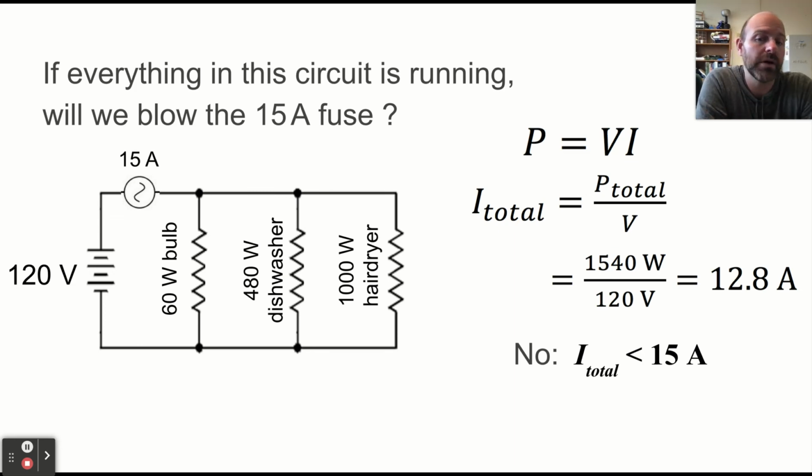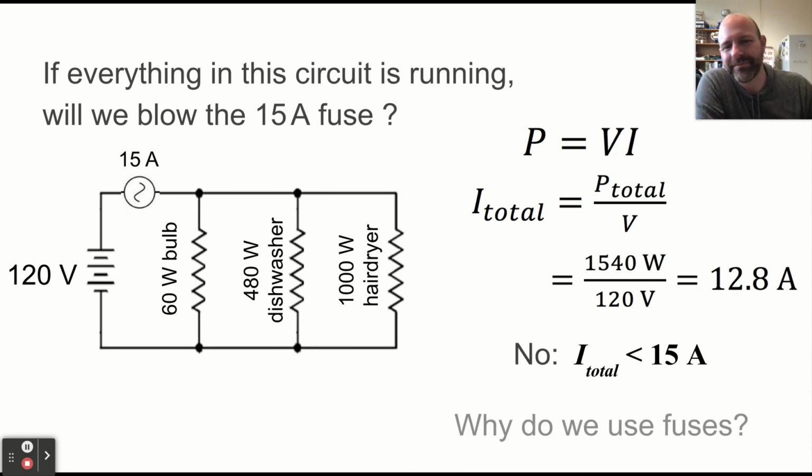If we added one more, even a 60-watt light bulb, would that be enough to blow the fuse? I guess that wouldn't be, right? No, that would be another half an amp, and we'd be okay there. Oh, good. So we could turn on one more light bulb.